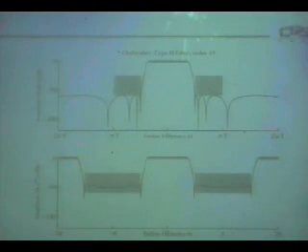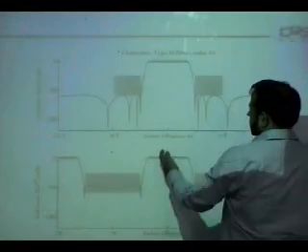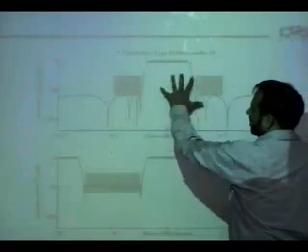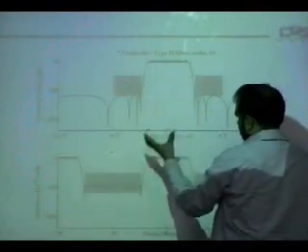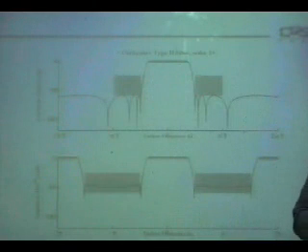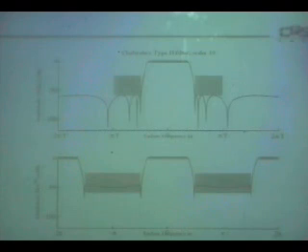There will be aliasing. It may be misleading for you, because you are happy with the analog filter, but when you convert it to a discrete time filter it won't meet specifications.